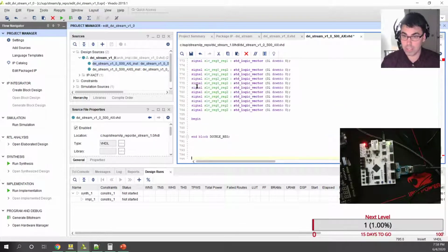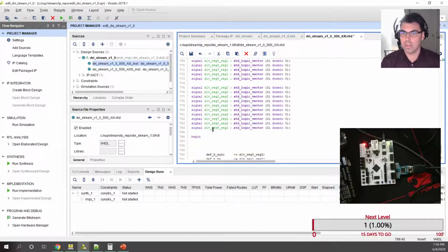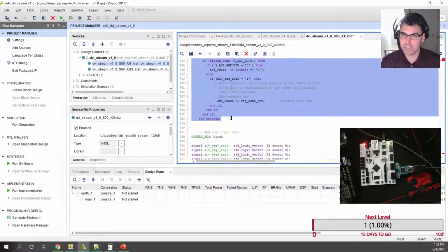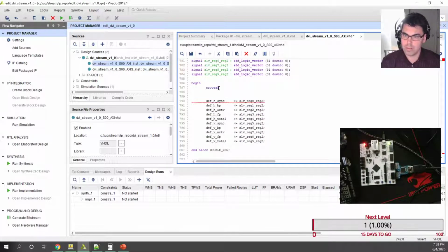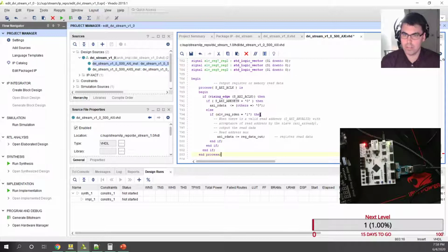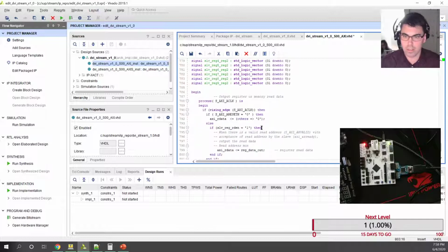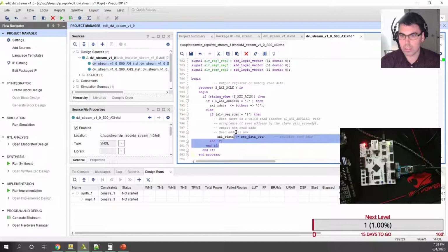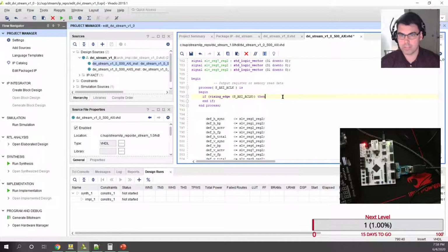And we want these to be in the scope of the block, right there. And then we're gonna need a process. And we're just actually gonna steal, just go ahead and steal this process right here. And if you don't need a reset, don't assign a reset. That's an important thing in FPGA design. Resets should only go to registers that matter. And since these are registers that are constantly being updated every single clock cycle, we can completely ignore the reset.